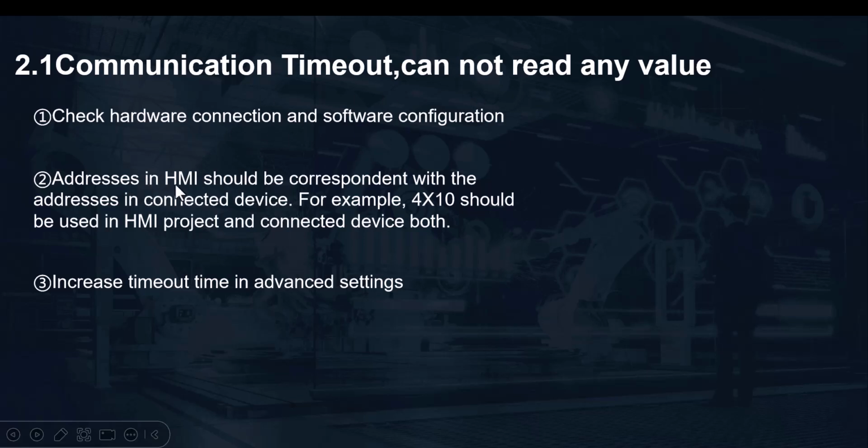And addresses in the HMI should correspond with the addresses in the connected device. For example, if there is a component bound to the 4x10 address, then this address must be used in the connected device as well. Otherwise, a communication timeout will occur.